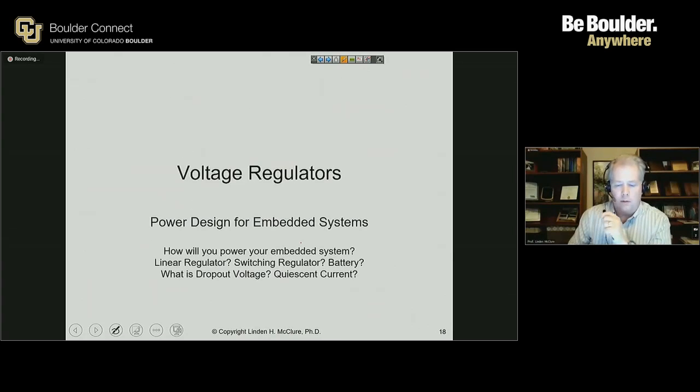Okay, before I go into voltage regulators, I'll pause. So if you've designed hardware before, have you added decoupling capacitors to your designs, or is this a new concept to you? New concept. Okay, so think about this as you go through the lab assignments. It's actually one of the checklist items on our labs this semester. Did the student add decoupling capacitors? So if you just think up front, okay, every time I add something on, I should be thinking about adding some decoupling capacitance, you'll be in good shape.